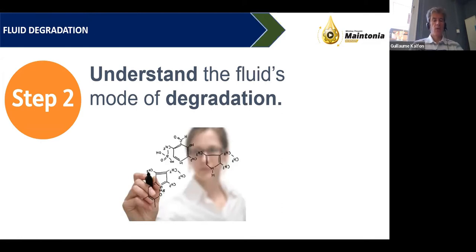Okay, if we have moisture in oil, we understand why. It means water has ingressed into the oil. Or some hard particles can be dust ingress or can be a sign of wear, depending on what the particles are made up of. But varnish is not so intuitive. Where is this thing coming from?